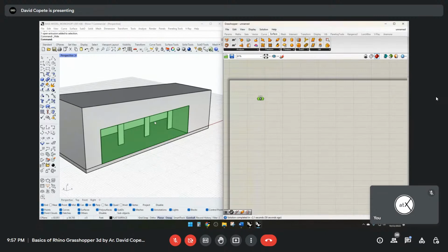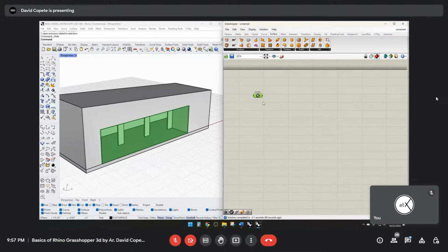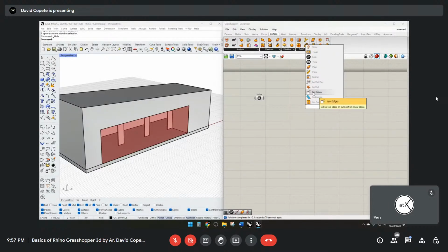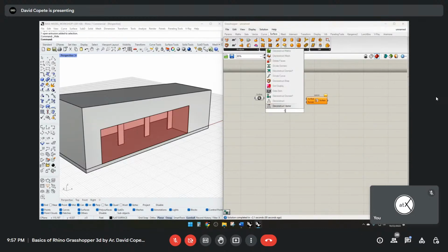And with isotrim, you actually have other ways of taking that pattern and making other custom patterns. So when we have a surface, we're going to bring isotrim. Now, isotrim is what subdivides the surface, but you have to bring in two components. Number one, isotrim. Number two, divide domain squared.